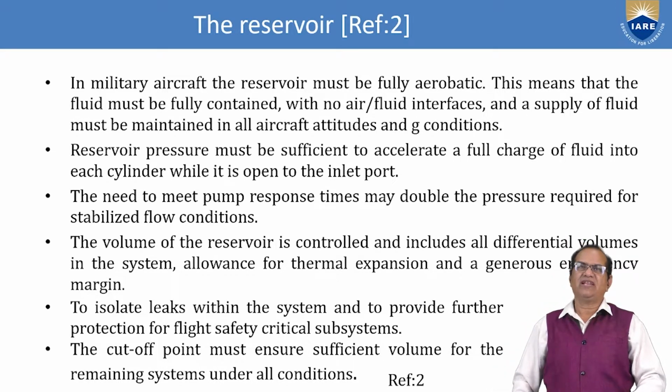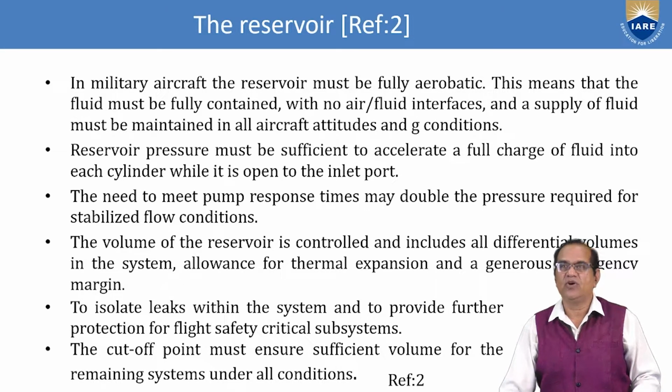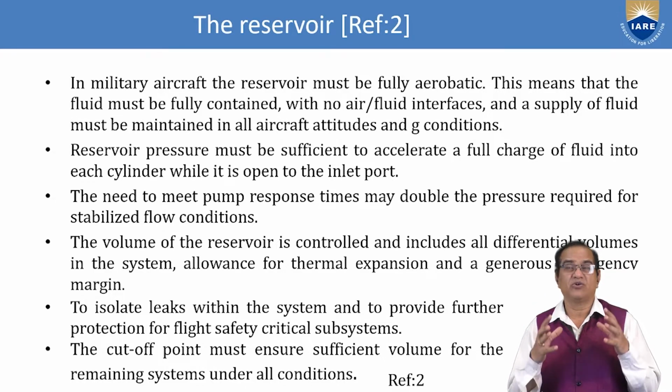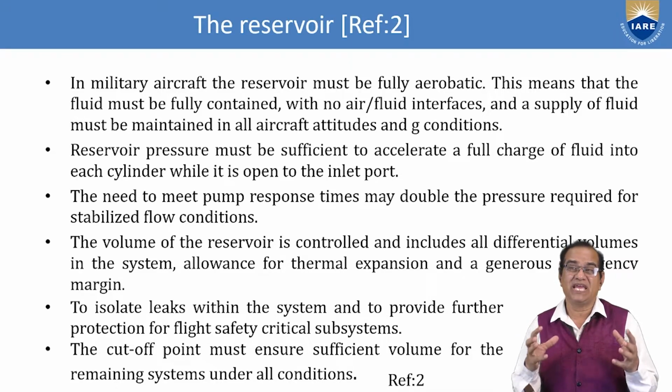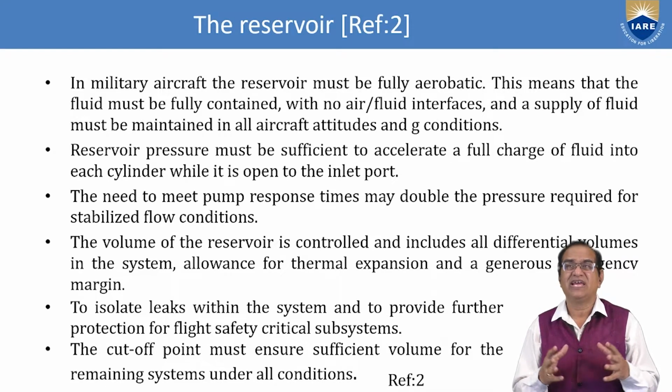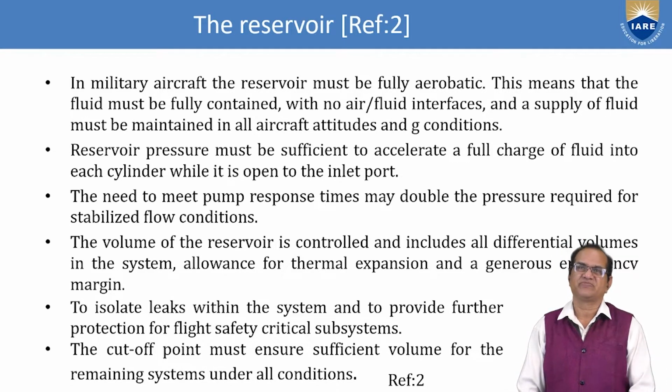So the reservoir, in military aircraft, must be fully aerobatic. This means that the fluid must be fully contained with no air-fluid interfaces, and a supply of fluid must be maintained in all aircraft attitude and G condition. Especially for military aircraft, your reservoir should be in such a way that there should not be any leakage, there should not be air and fluid mixture anywhere. Supply of fluid must be maintained in all aircraft attitude and G conditions.